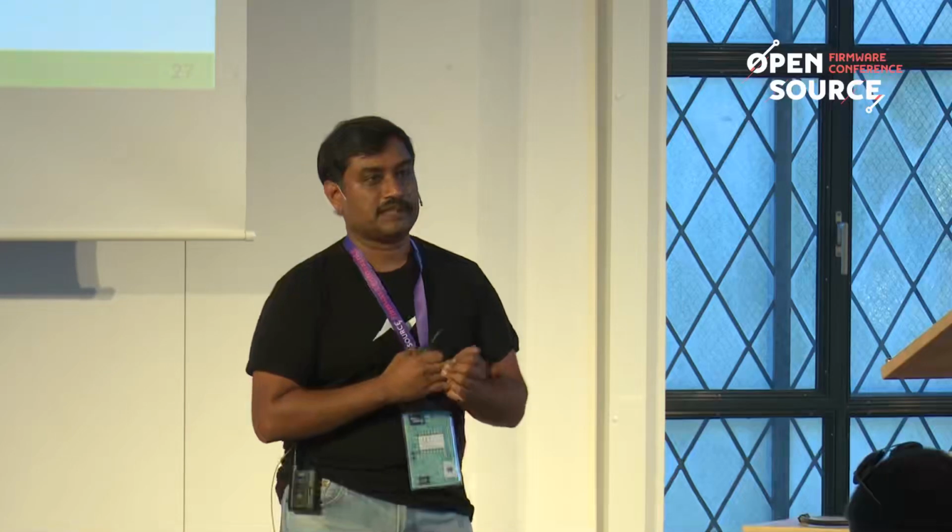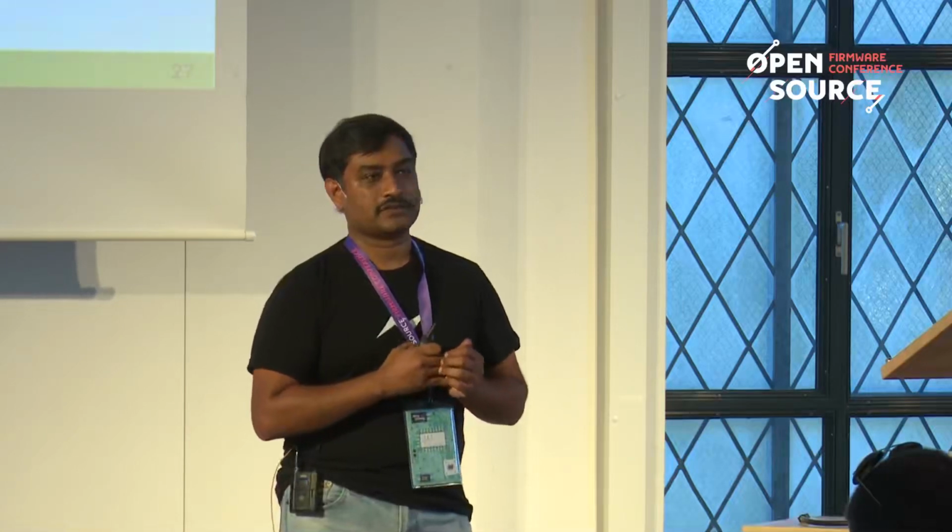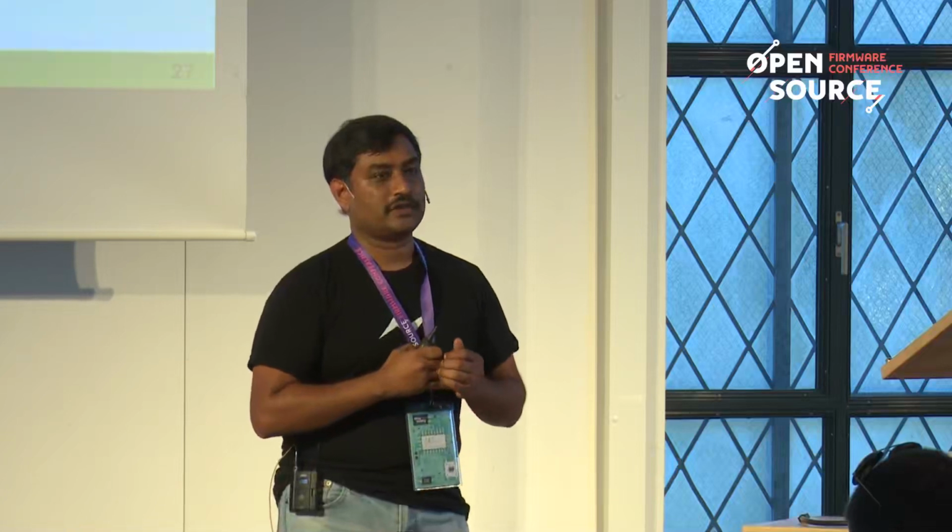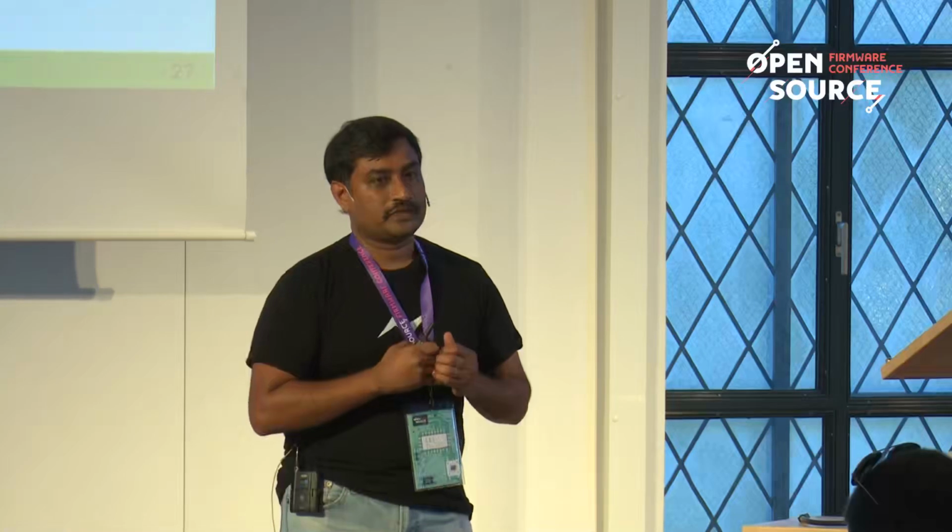So we looked at, is there any open source alternative? We thought it's been 20 years, so somebody might be having an open source solution, but guess what? We couldn't find any single open source solution for this. So we took an approach of, why don't we do it ourselves? We took the BMC vendor's SDK and then used Yocto Linux BitBake as the build system, and tried to create this BMC firmware, OpenBMC.